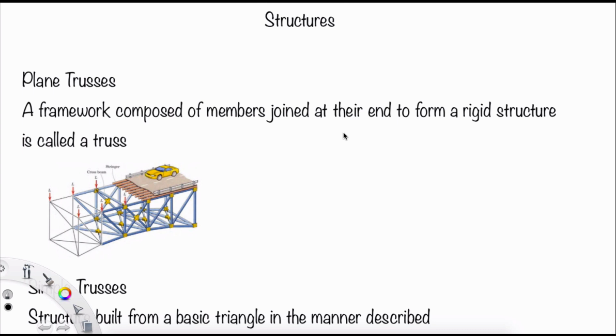The basic procedures in this chapter have been developed in the previous chapter, in the free body diagram. Isolating a body by constructing a correct free body diagram is essential for the analysis of statically determinate structures.